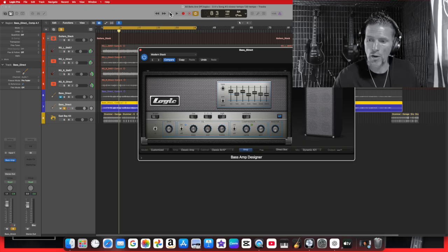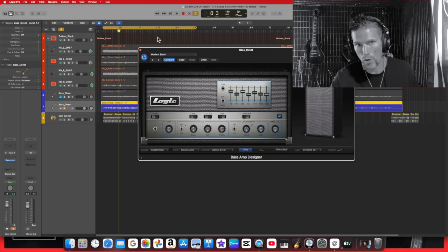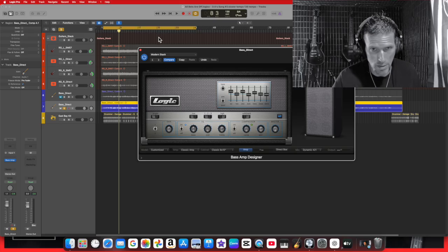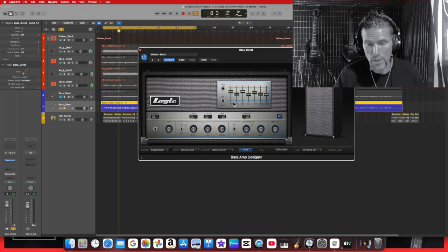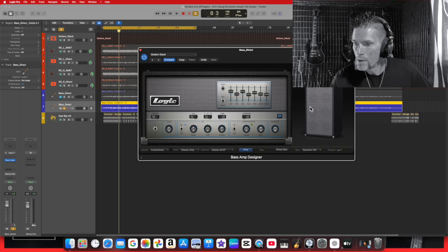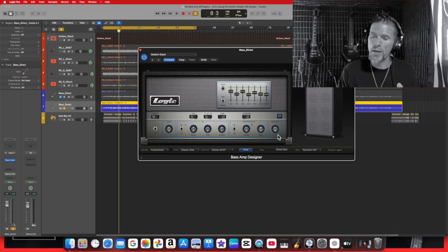Okay. So it's good to check and make sure it's not clipping that signal, and that you're around -6 decibels, and around -20 to -18, -21 in the RMS area. If you know what I'm talking about. If not, I'll have another video showing you how to use a VU meter or a level meter basically. Okay. So, but what I was getting at here is sometimes you'll record your signal a little too quiet,